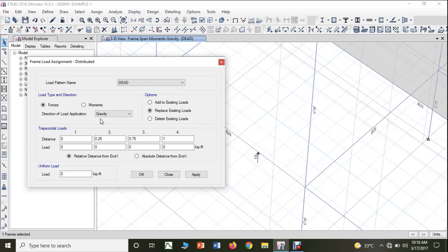Now when it comes to the distributed, we have mainly two types of loading acting here. One, we call it as uniformly distributed load. That means for every 1 meter or 1 unit distance, your intensity of the loading is going to remain the same. For example, in feet, you have a 10 feet beam, so for every 1 feet the intensity of loading is going to remain the same. So then we call that as uniformly distributed load.